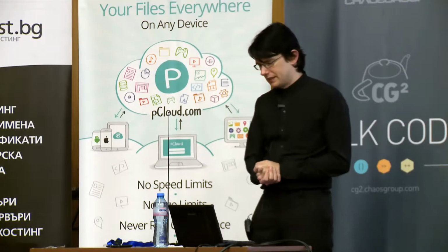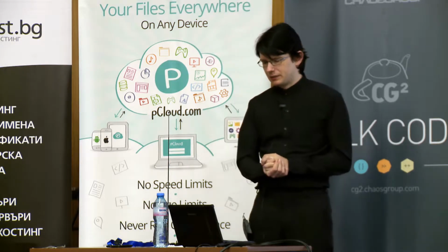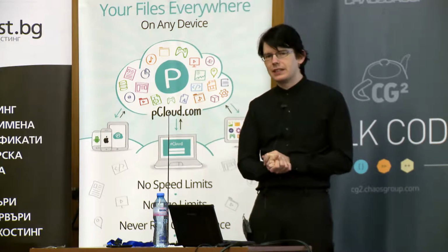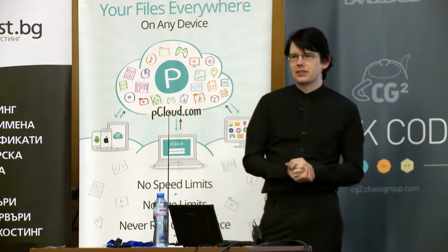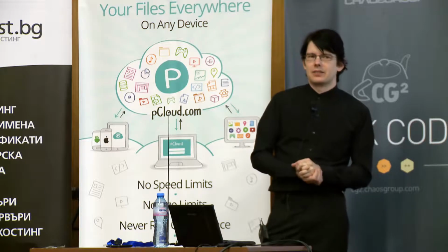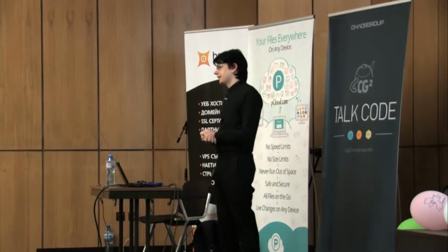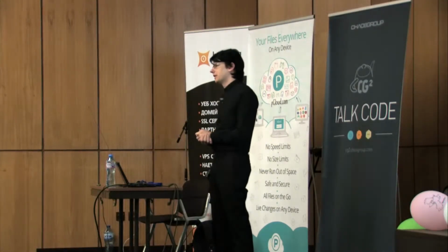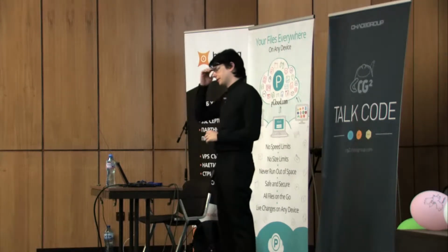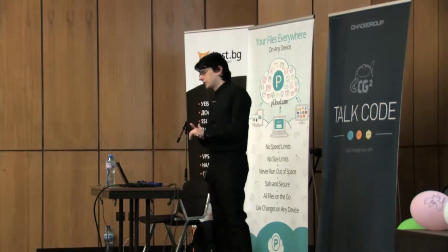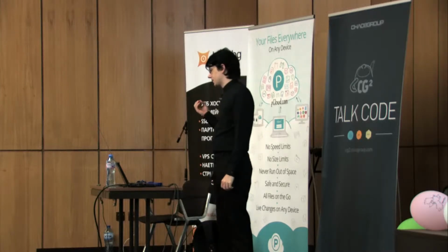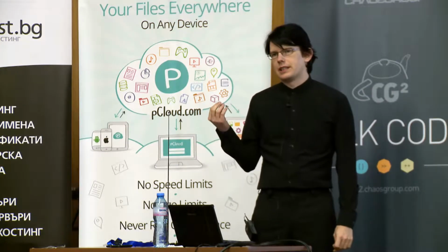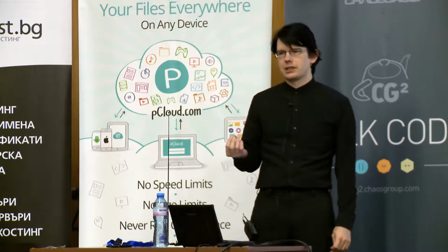So what happened is that I actually don't know at which point in time, I would also guess around 2009, 2010. Realtek, probably everyone has heard that name before, is a Taiwanese manufacturer of all kinds of silicon. Starts from Ethernet chips, that's what most people know them for, but they also do all kinds of other chips. And what they built is a chip called RTL2832U, which is a single chip receiver for digital TV, digital broadcast TV.